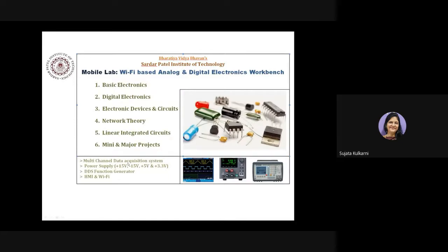So the system should have a multi-channel data acquisition, and the power supply should be at least plus 15, minus 15, plus 5, 3.3 volts. It should not only have a function generator, but a digitally synthesizable function generator. And of course, user interface, HMI part, as well as Wi-Fi part, because we want to put it on the internet. It's cloud computation and remote access for evaluation purposes.